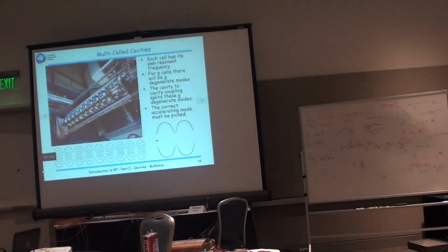Okay, so I'm going to have to switch to my other plotter. For multi-celled cavities, you can think of a transmission line type cavity as a multi-cell cavity. It's got 2 cells, 2 transmission lines, connected in the middle by a gap capacitor. So that's considered a 2-cell cavity. You could have had a 1-cell cavity. You could have just kept that short circuit over there and not put another transmission line there if you'd like to. People do that with cavities.